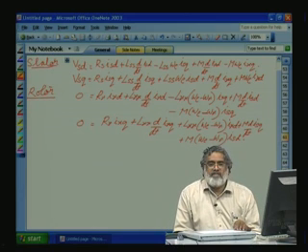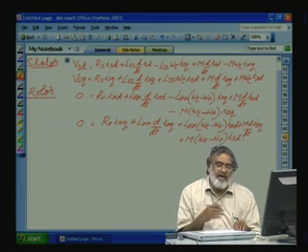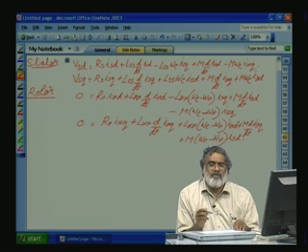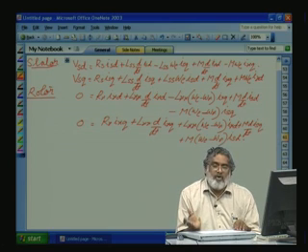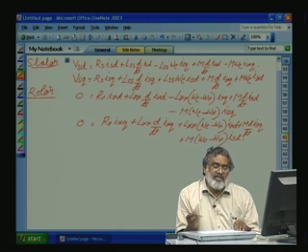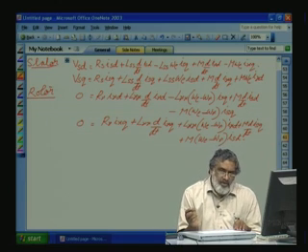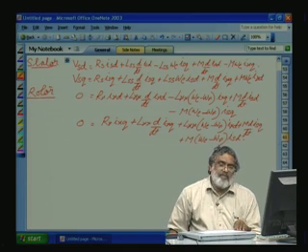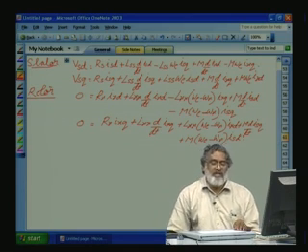Now, based on these dynamic D and Q equations, see what we did. First we defined the voltage space vectors for the stator as well as the rotor with respect to the alpha beta reference frame axis. Then we transformed the whole voltage term to the general rotating reference frame axis dq. The position of the general rotating reference frame with respect to the alpha beta axis is rho at any instant, and the speed of rotation is d rho by dt, which is omega rho. Then we separated into real and imaginary components, the D and Q components. Now we have the dynamic equation under all conditions, that means when the amplitude as well as the speed or frequency varies.